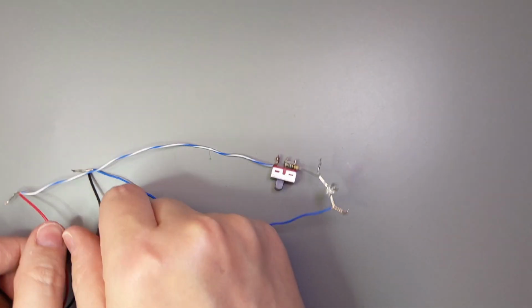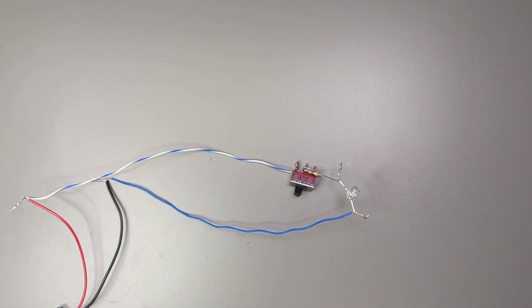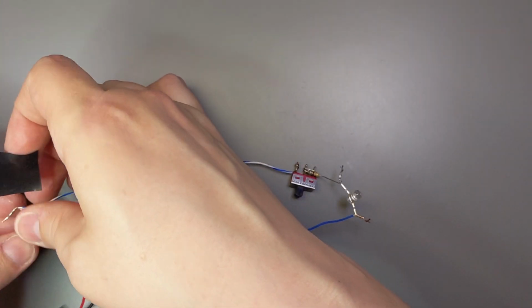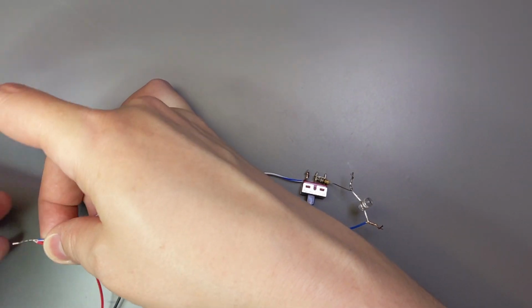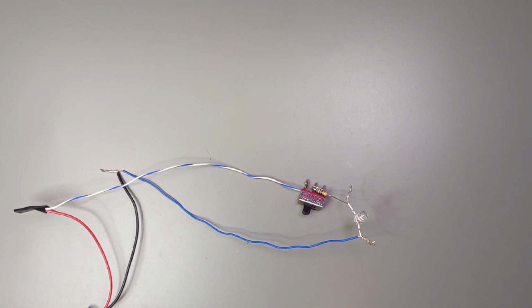Keep an eye out for wires that might short the battery. Here I have 2 bare wires that are about the same length and could easily bump together if I move them around. A little bit of electrical tape on just one will prevent any shorts. If I were to wire this up more permanently, I would add some insulation to any joint that can move around freely.